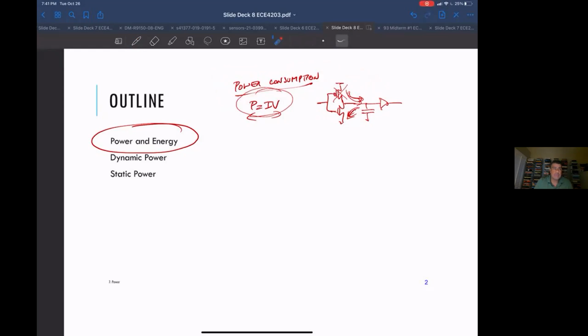The reason we're looking for an average power consumption is that instantaneous power consumption means that particular nanosecond, picosecond, that was your power consumption. But what does it mean for how many minutes your cell phone can operate? That power consumption is changing with time as your circuit is doing different things. So you have to look at the average power consumption over some reasonable, interesting amount of time. It depends on your system operation.